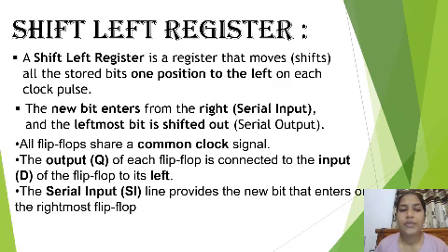The shift left register. A shift left register is a register that shifts all the stored bits one position to the left on each clock pulse. The new bit enters from the right, meaning serial input, and the leftmost bit is shifted out. It is a serial output. All flip-flops share a common clock signal. The input of each flip-flop is connected to the output of the flip-flop to its right. The serial input line provides the new bit.